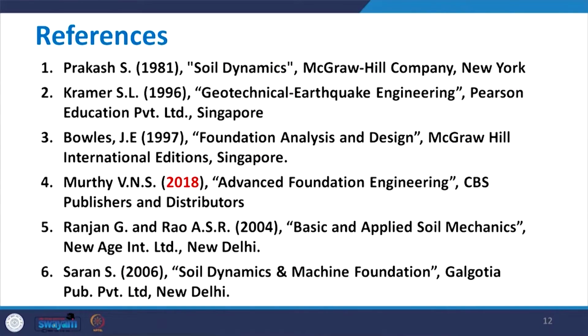Then the second book, which is very famous, by Stephen Kramer, published originally in 1996, is on geotechnical earthquake engineering. This will give the basic background on the dynamic soil properties, liquefaction and ground response analysis. Then the third one, which is by Bowles, is a very practical book with numerical examples on foundation analysis and design,